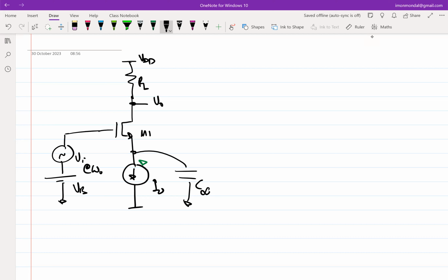You are making something on the breadboard. You cannot put an infinite capacitor. You have to put a finite value of the capacitor. So given that your signal frequency is at omega naught, what is the constant on C infinity that you need to ensure, so that at those frequencies of omega naught, the capacitor acts as a short circuit? So what should I do?